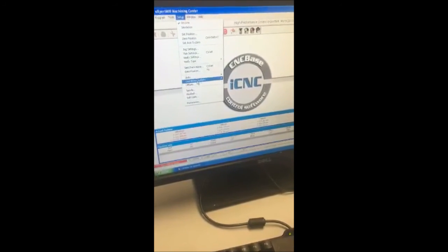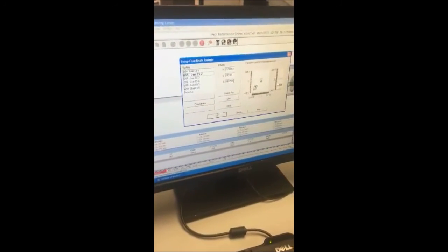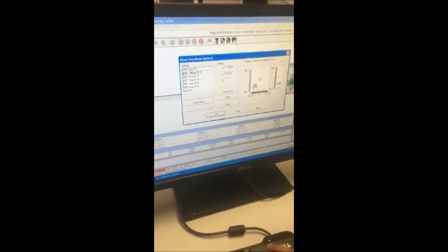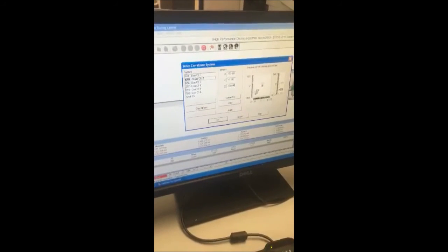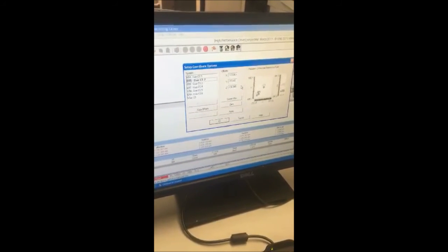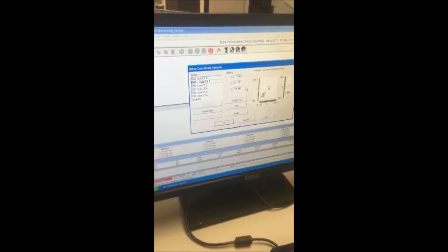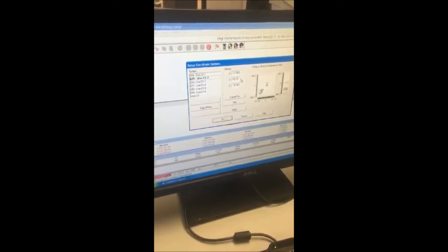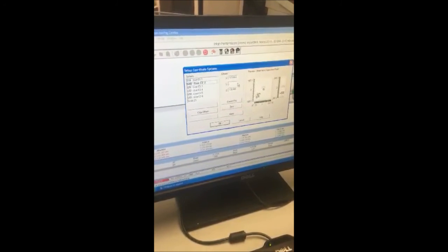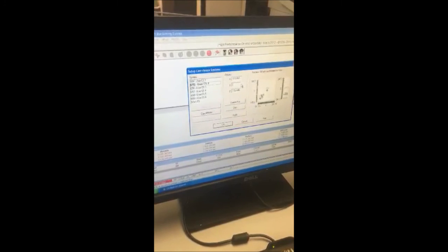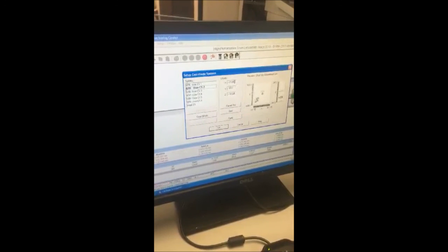Set up, coordinate systems, set up again, and then you change these numbers for the numbers you calculated. In the case of Y and X, you need to take out the radius of the tool, so that your part 0 would be the part that you want, because it is based in the center of the tool.